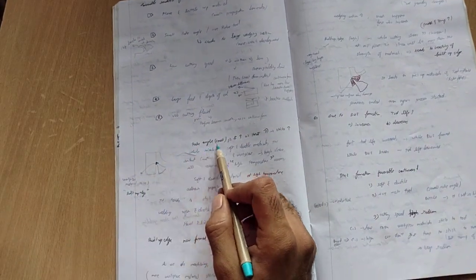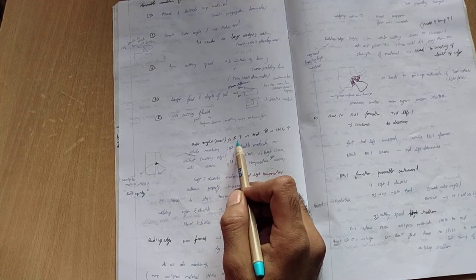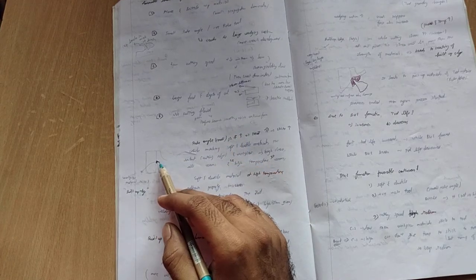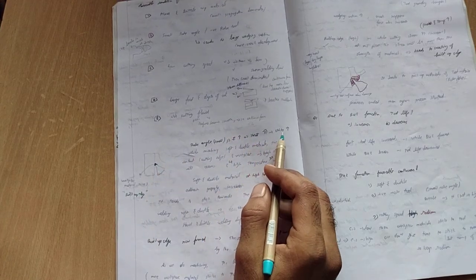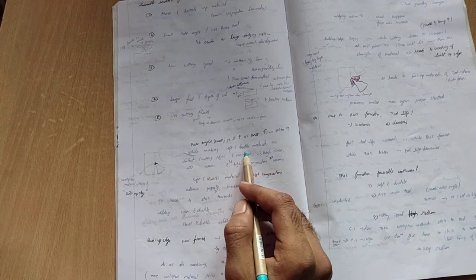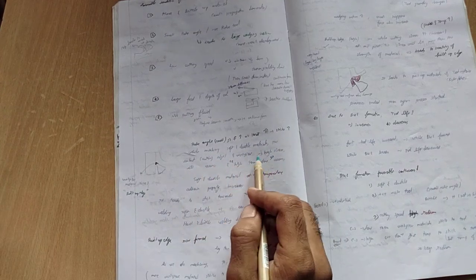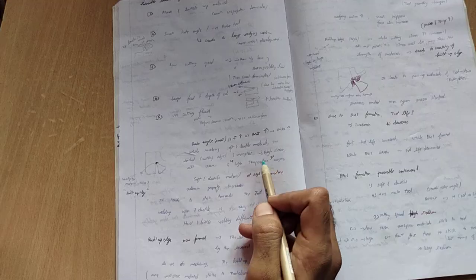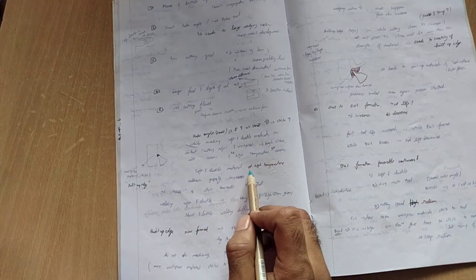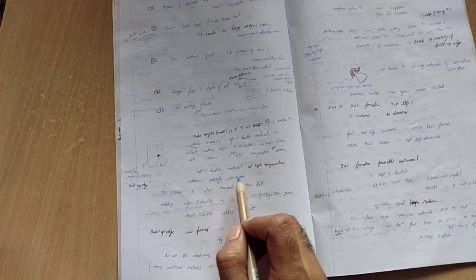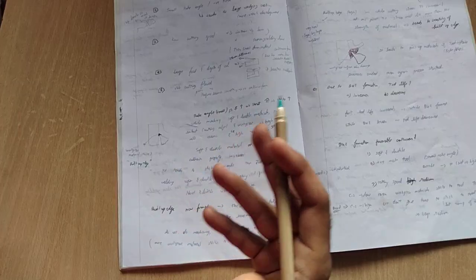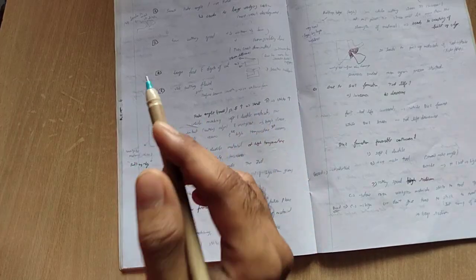So you can see whenever the rake angle is small, the cutting force is so much higher. The rake angle is small, the cutting force is high, and the heat is also very high, and the material sticks. While machining soft and ductile material, the contact with the workpiece has the highest stress, so high temperature occurs. At high temperature, the adhesive portion of soft and ductile material increases, so definitely the cutting will occur, and the built-up edge will also definitely occur.